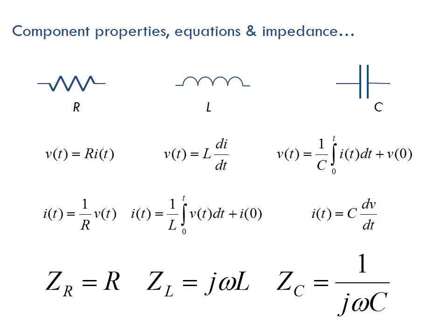However, when we get to more complex things that change and have different frequencies and sinusoidal properties, impedance becomes much more complex than just R or just a solid value. It becomes an equation that we can calculate out. So that's going to be important coming up. For now, for a resistor, impedance and resistance are about the same.